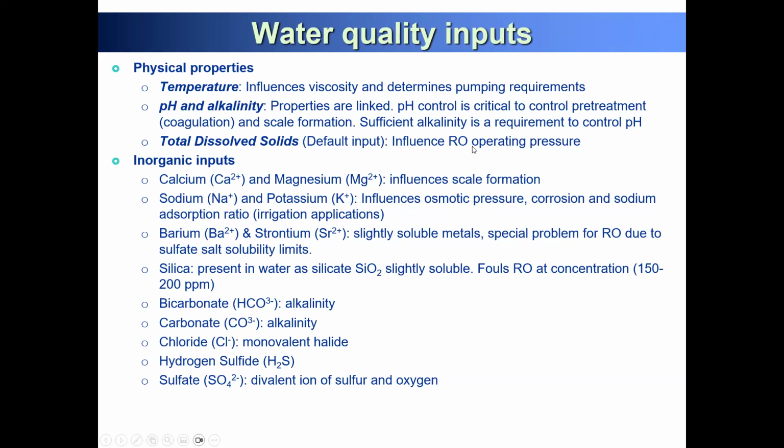And TDS influences the RO operating pressure. So TDS will give you the overall osmotic pressure, so which pressure will be best to recover 50% recovery rate. So this is the physical property you had better include in your software as a minimum. Inorganic inputs: calcium and magnesium are among the strongest inorganic scaling potentials. So if you can put in this information, calcium and magnesium, you will have a better idea of scaling formation.